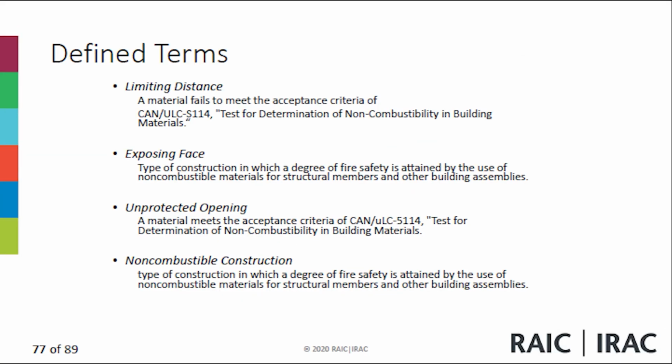So let's take a look at this closely. A street is any highway, road, boulevard, square, or other improved thoroughfare that is 9 meters or more in width. So if you look at a driveway of 6 meters or less, that would not count as a street facing the building. That has been dedicated or deeded for public use and is accessible for fire department vehicles and equipment. Now you can have a private road that is 9 meters, and it is accessible by the fire department, and it can take the loads of the fire department vehicles and equipment, and the fire department says it is usable, then it is considered similar to a public street. So it is dedicated for use and accessible for the fire department.